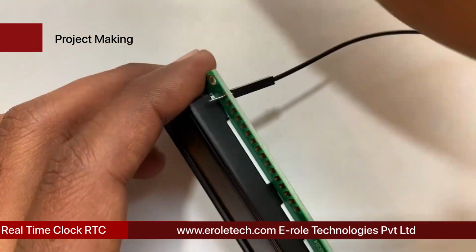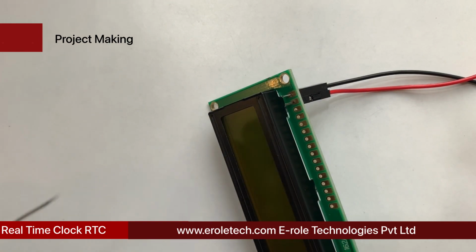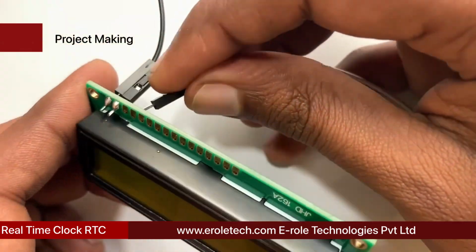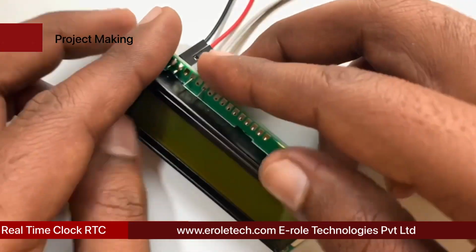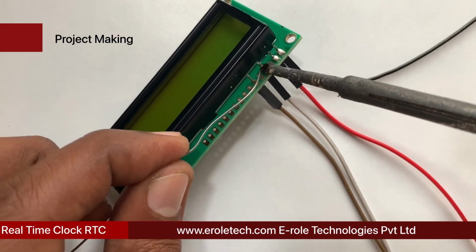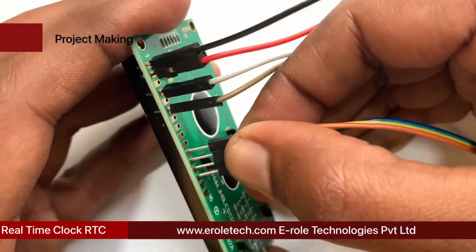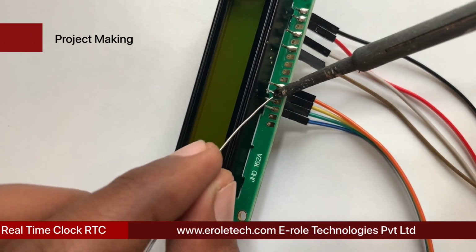Now we will solder a black wire at hole number 1 and red wire at hole number 2 of LCD display. Now we will solder a white wire at hole number 4 and brown wire at hole number 6 of LCD display. Now we will solder orange, yellow, green, and blue wires at pin number 11, 12, 13, and 14 of LCD display.